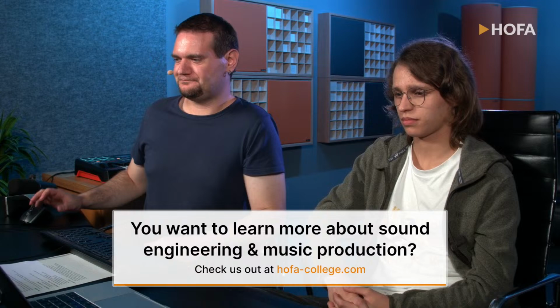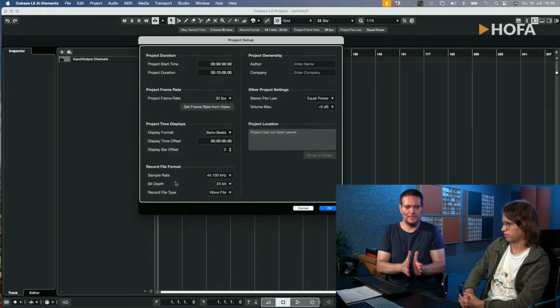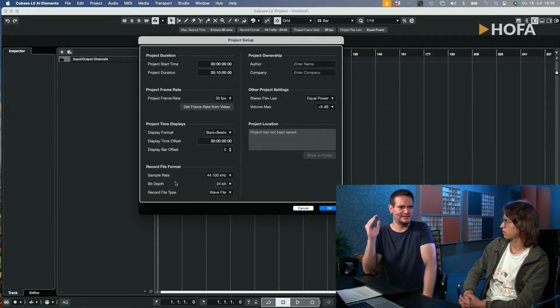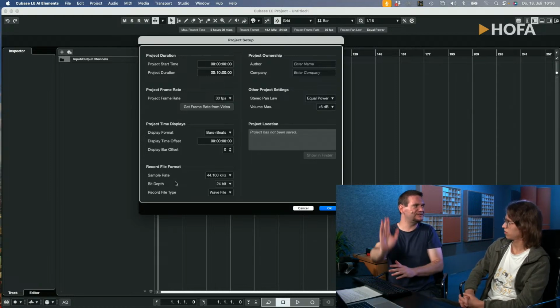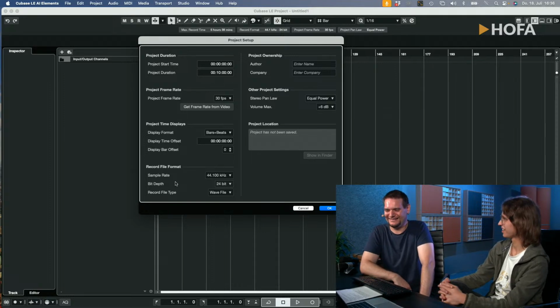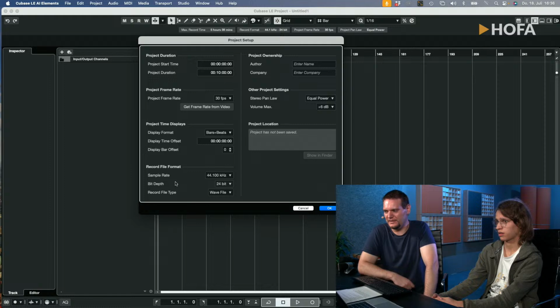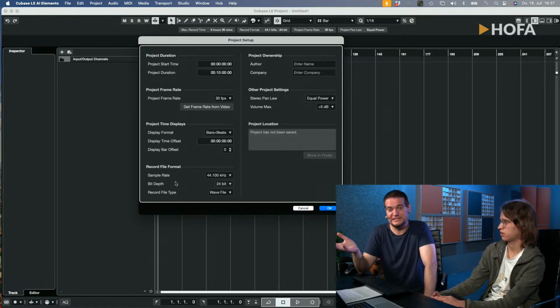Okay. The bit depth is the other important parameter that comes to mind and has to be set. It also has to do with your final aim. Where do you want to go? And the bit depth is something like the dynamic range, so from the lowest parts in sound to the highest parts. So it comes to actual volume. So from silence to, let's say, a jet starting from the airport. That's a good way to say dynamic range. Yeah, and you have 6 dB per bit, and nowadays the 24-bit format is something like a standard. Usually your DAW is able to work in 32 or even 64 bits.